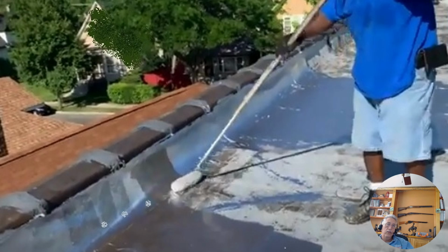So I mentioned silver coating before. On those old technology roofs like torch downs and built-up roofs, they will silver coat them like this to protect them. That's not just a paint, it's a waterproofing product. Here in the Detroit area, there's one called Durabright, and Henry makes it. It's thick, like a paint, but when these roofs get old, they crack. They call it alligatoring, and that product is made to fill those cracks in to waterproof it, and then it's silver to reflect the sun and the heat off the building.